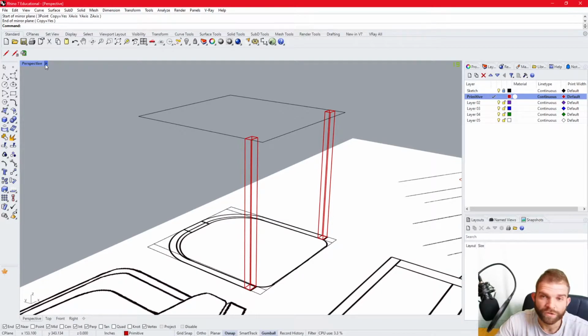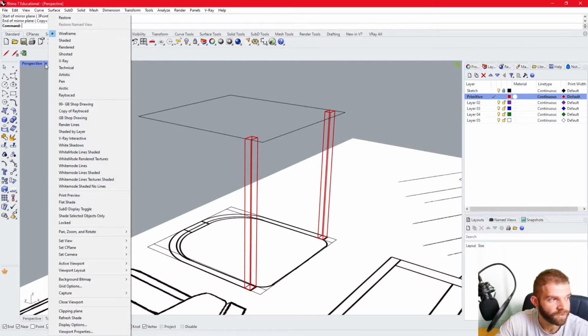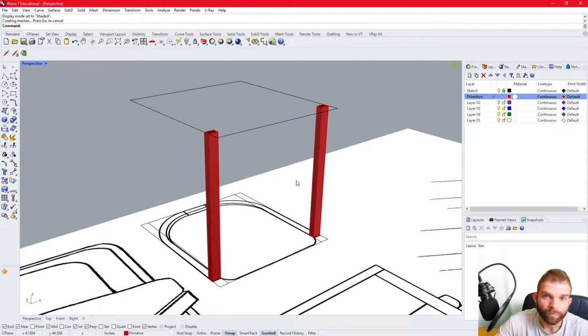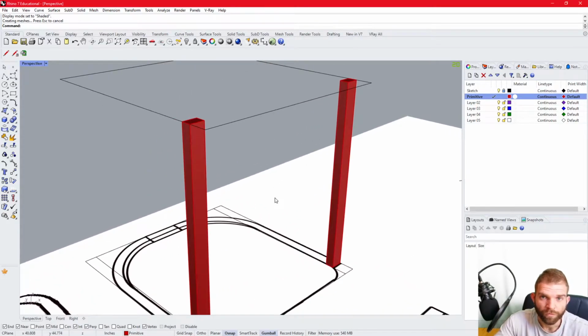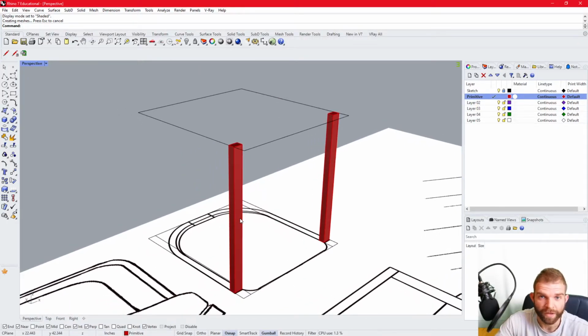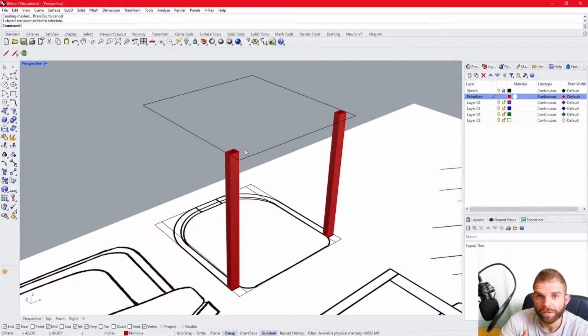And now I'm going to start manipulating a lot of 3D objects. So I'd like to switch to my shaded view. I'm going to select this drop down arrow right next to perspective and select my shaded view. Now I can preview my 3D geometry as solids. This makes it easier to move around the model, and I can always switch back to wireframe if there's any instance that it becomes easier to use that. There's many different ways that you can build geometry in Rhino. You can continue to use the commands I've been using, such as box and mirror, or you can also copy paste these boxes and then select each face individually to then drag them or resize them to wherever you'd like. I'm going to show you a little bit more of that.